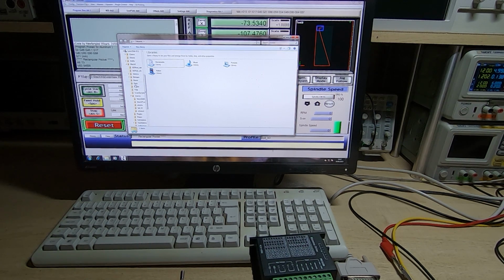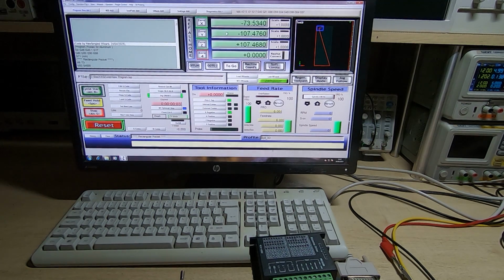So we have the MACH3 folder, a subfolder called macros, and within that we will normally have another subfolder that contains all the macros for a particular machine that you have a profile for. Those macros contain all the information required to allow MACH3 to properly control a particular machine.